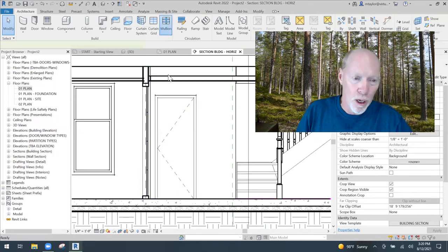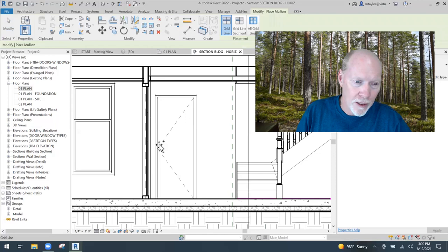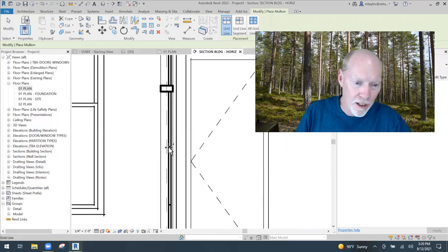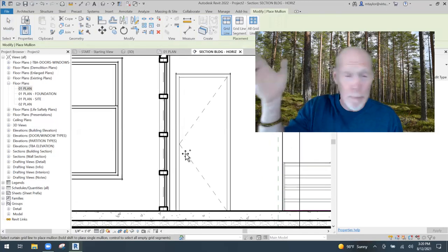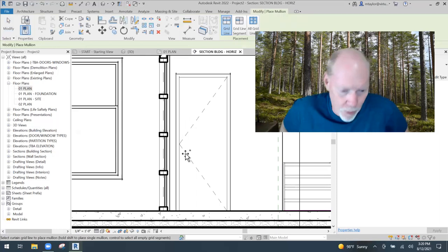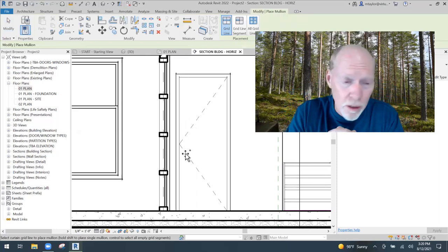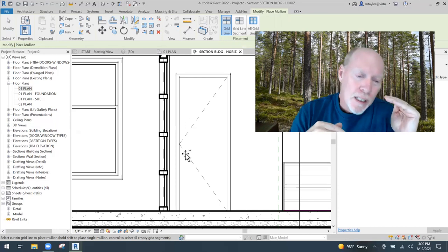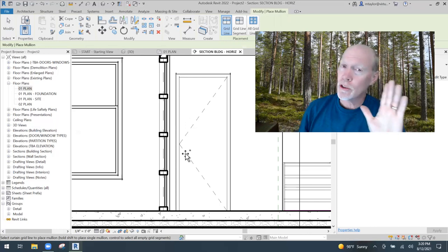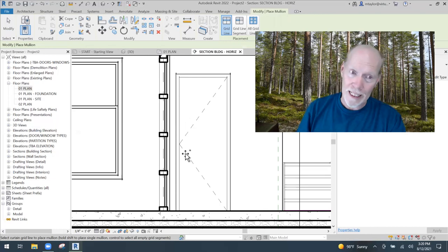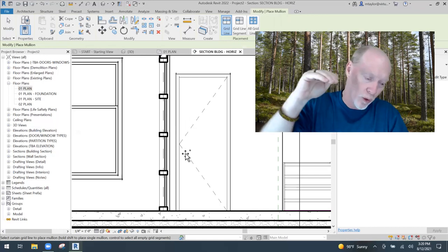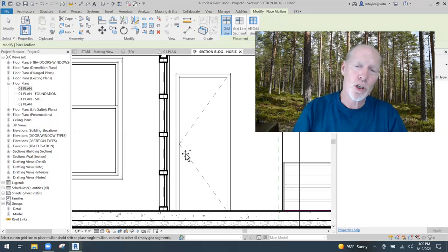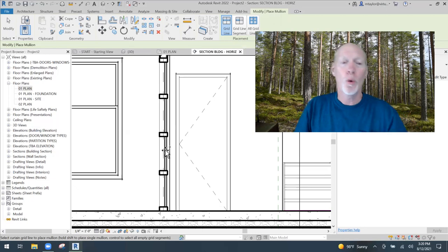And now I'm going to add a mullion. When I click right here, bing, a mullion pops in, and another one pops in there, and another one pops in there. And this is just the 2.5 by 5 inch mullion, which is typical in your project, probably. You may have a 2 by 4 mullion or whatever. These are just plain old rectangles, and they're good for designing and moving quickly. But when things get real in your project and you have a real Kawneer shape, I'm going to show you how to make real curtain wall mullions.